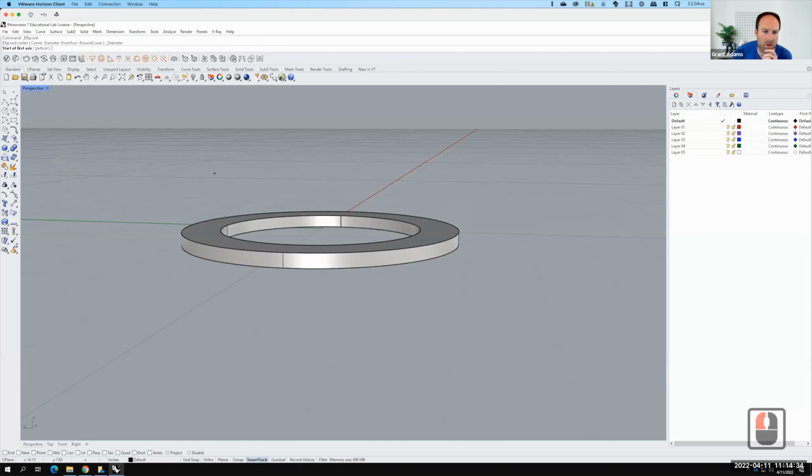It's going to ask me for the start of the first axis. I'm going to turn on my end snap, my quadrant snap, and let's turn on perpendicular as well. Oops, not intersection, perpendicular. So I can come over here. I'm snapping to this quadrant. The second point of the axis would be straight across there. Then I'd come to the opposite side, and again, we want to snap to perpendicular there. And now I have my third axis. So this is how big I want it to be.